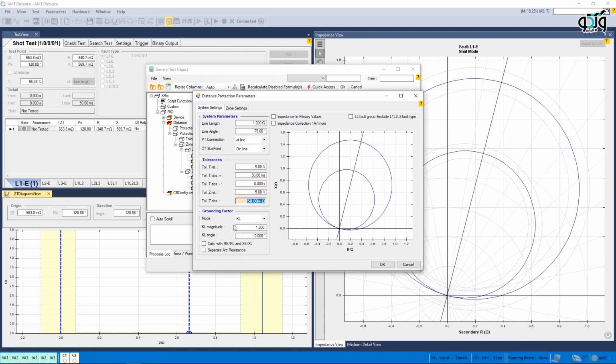In phase to ground faults, specifying this number in accordance with the relay algorithm is very important. If this factor is wrong, the calculation of the phase to ground fault will be wrong as well. So, one of the methods mentioned in this section should be selected in accordance with the algorithm used by the relay to calculate the single phase to ground fault.